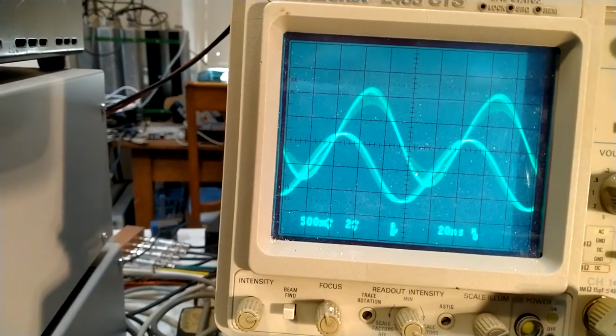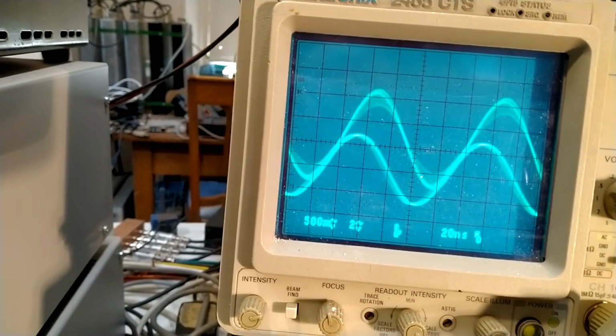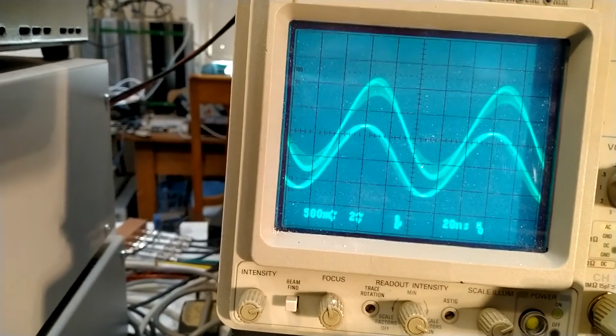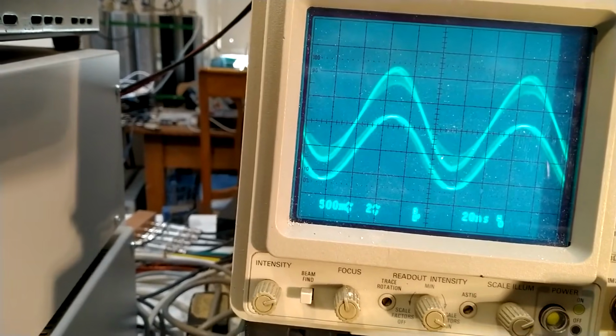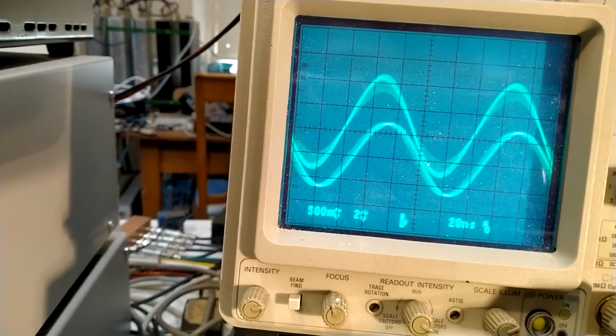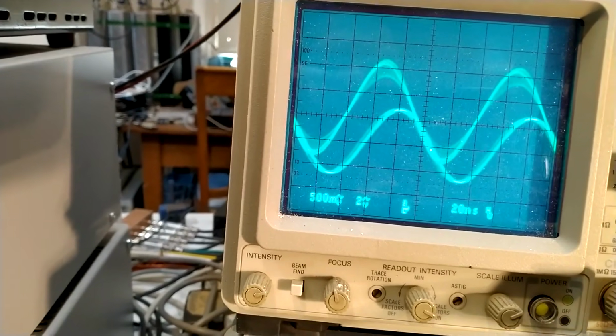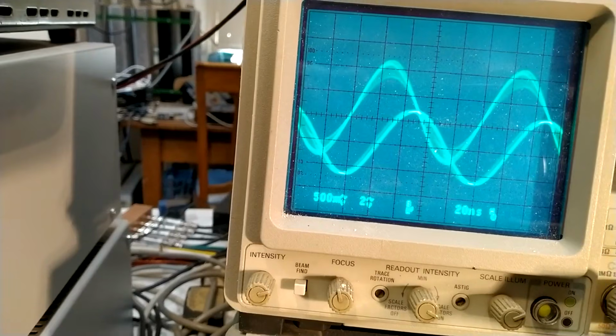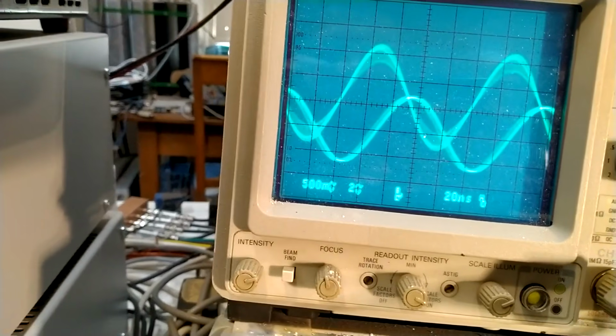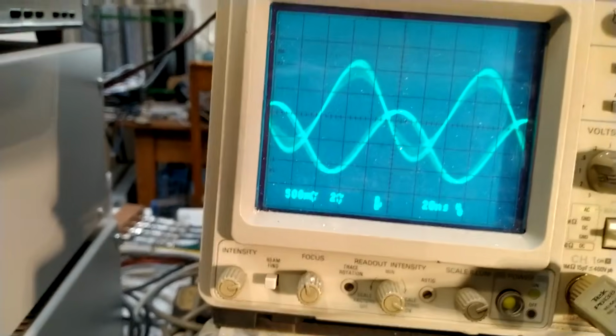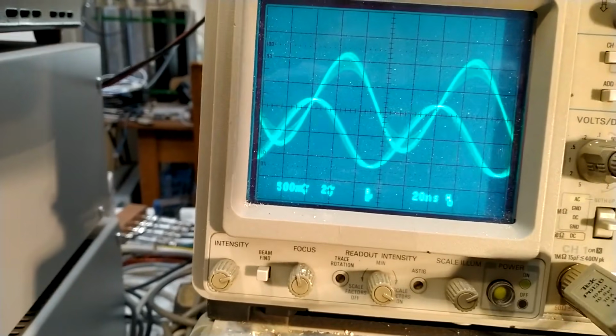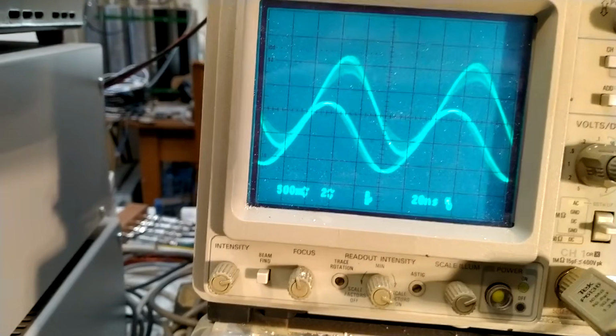It contains a little bit on the frequency on the other side of the 10 MHz, but that will not make any difference because the PLL will not let anything through that is far from the carrier. And the lower trace is the oscillator. If I put my hand somewhere on it, you can see how it drifts.